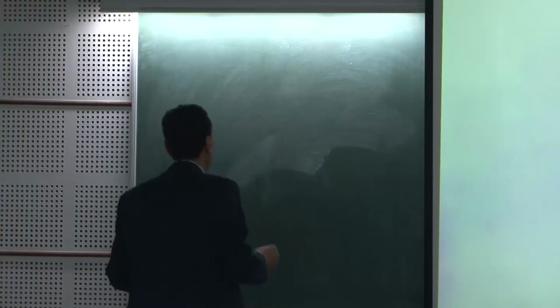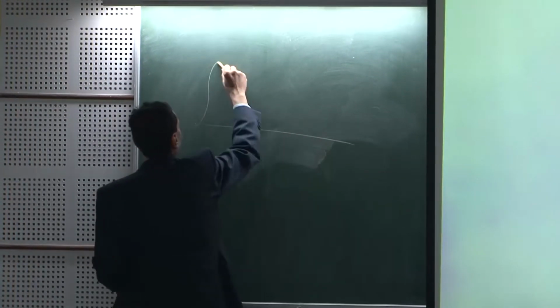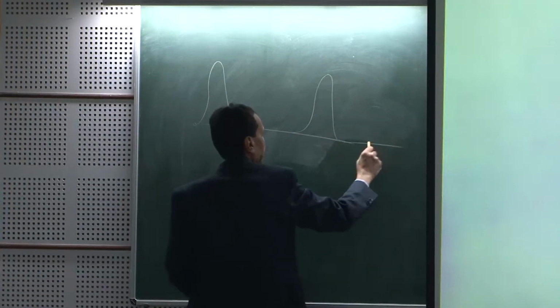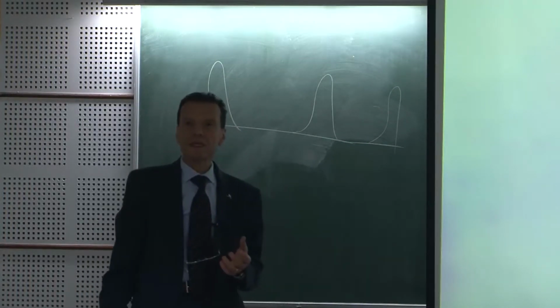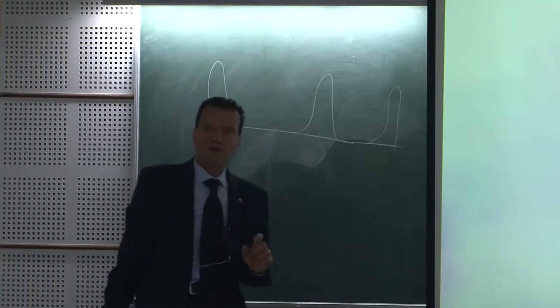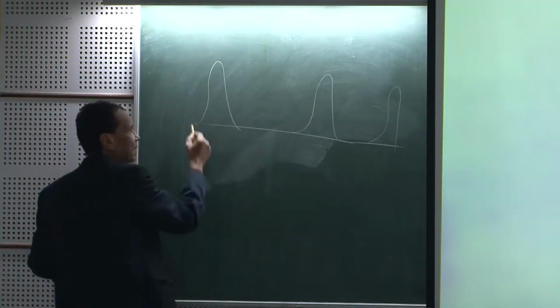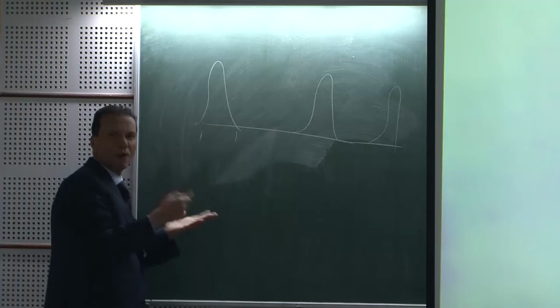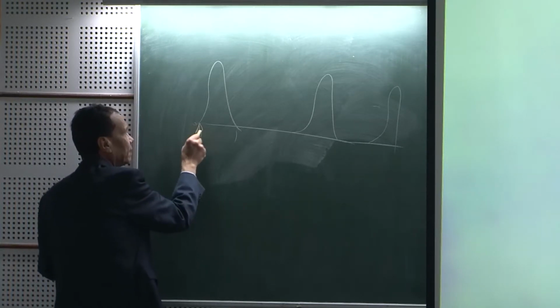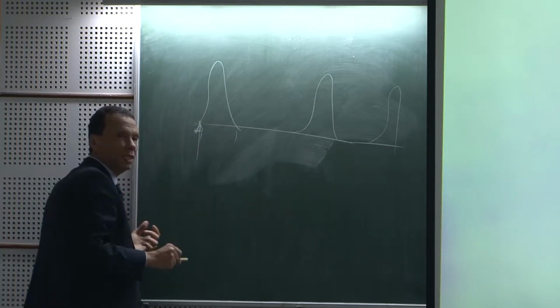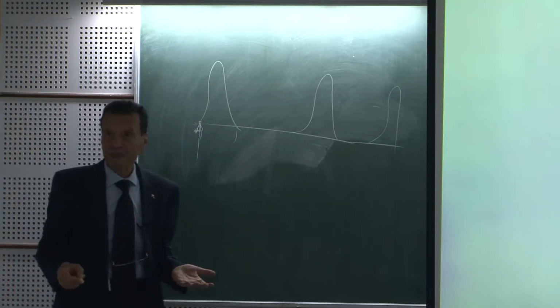So you measure something like that, which repeats itself. You don't have a fast digitizer, so you decide to do the following. Let us take the first sample you would like to cover here, say with 100 samples. You say, okay, I will fire my digitizer here to take this point. I'm not fast enough, so I will wait.